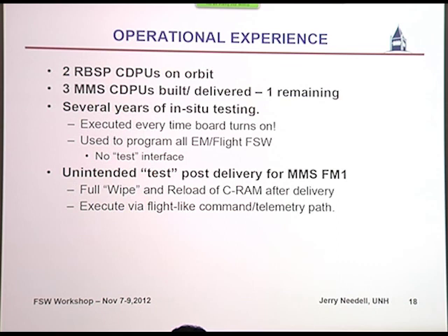The hardware part, no, because in this case we're kind of stuck. This is a requirement that we need to be able to provide this. In this case, there's no software involved in generating that data. The data is produced on power-on by the magnetometer, and the FPGA does the A to D acquisition capture. There's no software involved in creating that data. It's simply reading it from the device.